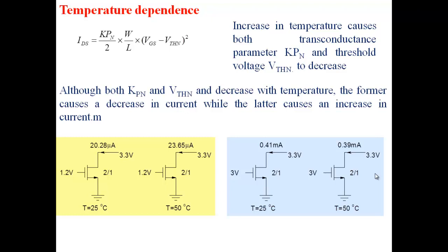So remember, we are talking about the MOSFET being on or off. When it's on, if my supply voltage is 3 volt, I'm going to apply the full 3 volts to my gate, right? So at that particular point, you may find currents are smaller. So this is at 50. If I go to 70, current may be even smaller here. So generally, as the temperature goes up, the currents are going to be smaller.